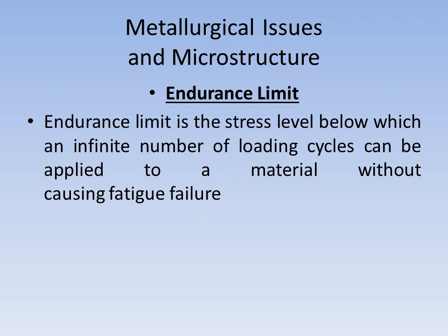Metallurgical issues and microstructure. A new term called endurance limit is mentioned while discussing the metallurgical issues and microstructure related to mechanical fatigue. What is endurance limit? Endurance limit is the stress level below which an infinite number of loading cycles can be applied to a material without causing fatigue failure. Here it is to be noted that if the stresses are below the endurance limit of the material, mechanical fatigue damage will not occur.